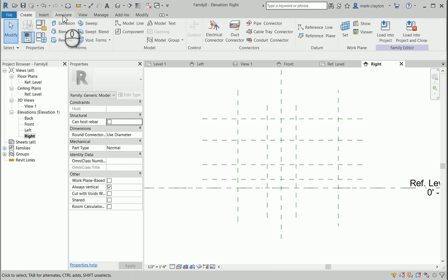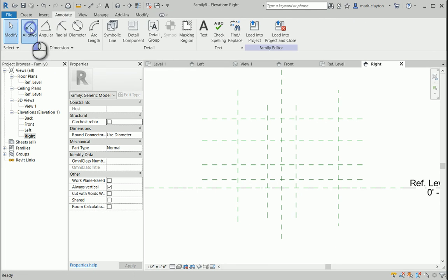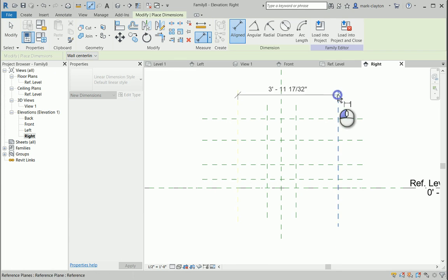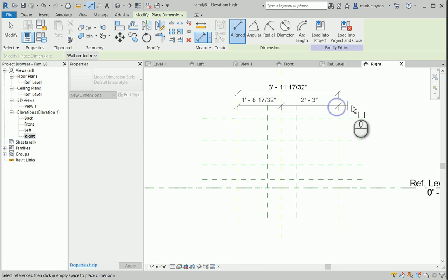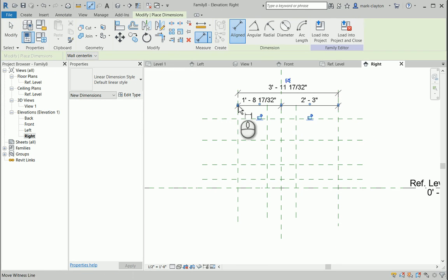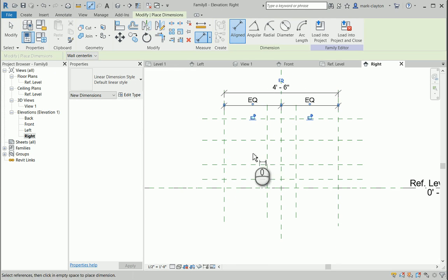So now I'm going to control this rigging in some ways. I know some things about this object. One, this is the width, but the width is symmetrical about this reference plane in the middle. So if I draw a dimension line for the width and a running dimension line that includes that center line, I can click on equal, and it's controlled to be equal. Similarly, the web has a width, and it's symmetrical, so I'll create a running dimension line and make it equal.